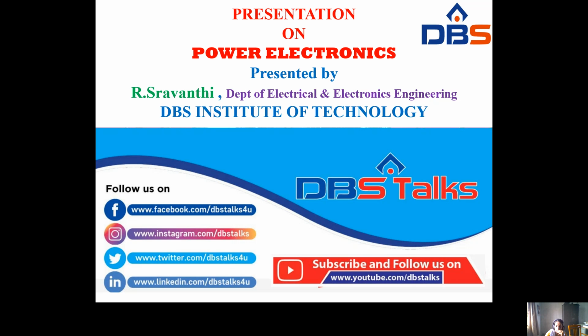So the thyristor will be conducting from 0 to pi plus alpha, and it will not conduct at 2 pi. So here T2 will be conducting. This means the thyristor voltage will be here. Okay. So VT2, the second thyristor voltage, is minus Vm. So from alpha to pi, the thyristor T2 voltage will be there.